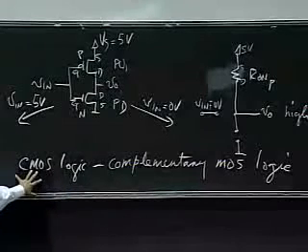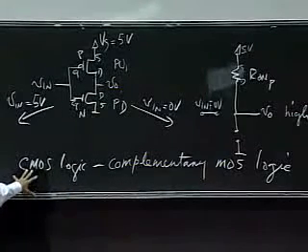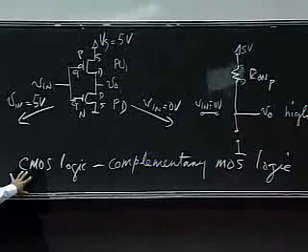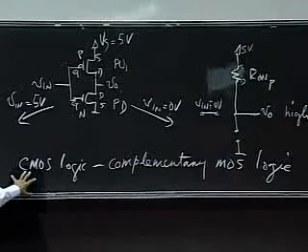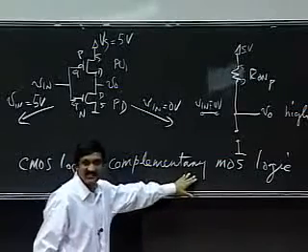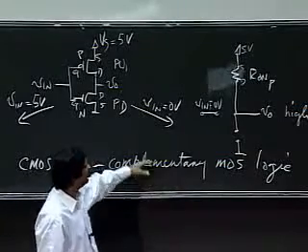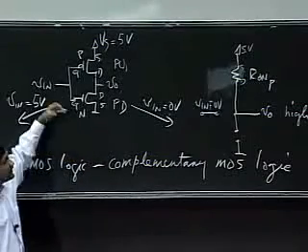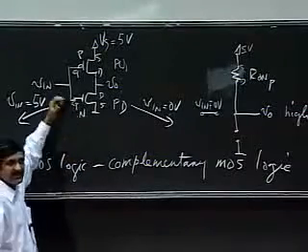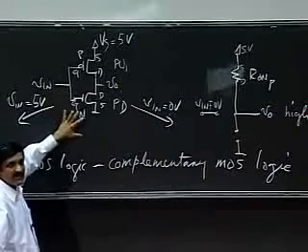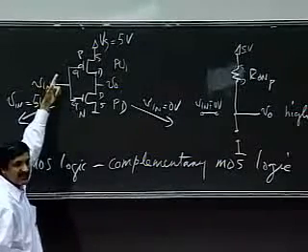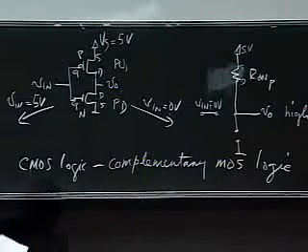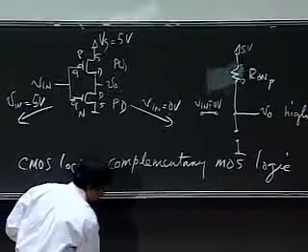That's what CMOS comes from. Okay, so I'm sure you've read in a number of places that most digital chips today use CMOS technology. It comes from complementary MOS, and complementary comes from the use of complementary transistors. N-channel, P-channel. Turns on when high, turns off when high. Turns off when low, turns on when low. Okay, they're exactly complementary to each other.